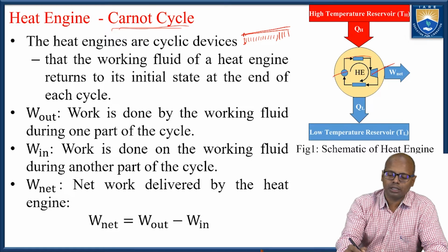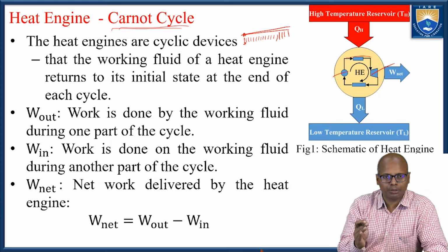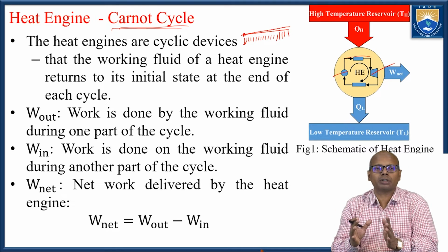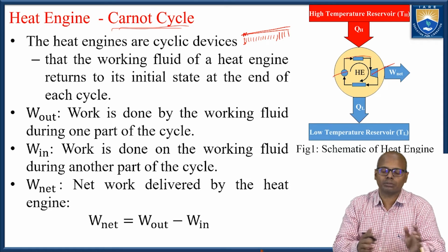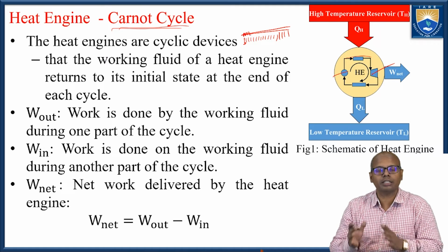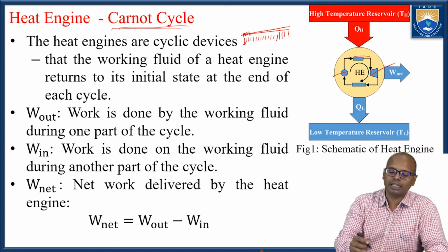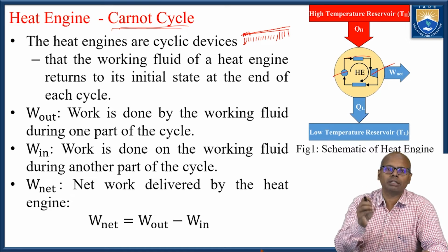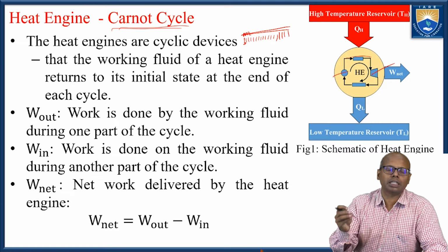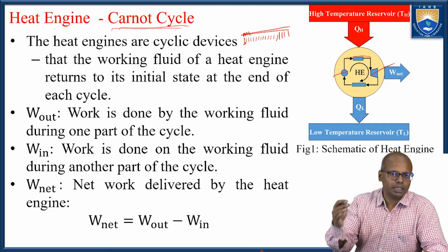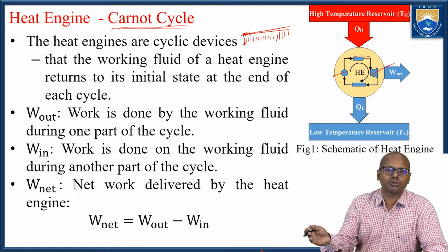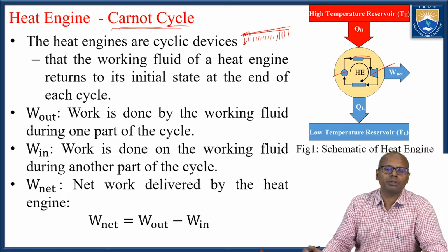From here to here the process happens and the entire system comes to equilibrium, and again some process happens, and again the system comes to equilibrium. Like that, at infinitely small intervals of time the process executes, and at each interval it comes back to equilibrium, and then goes to the next time step.